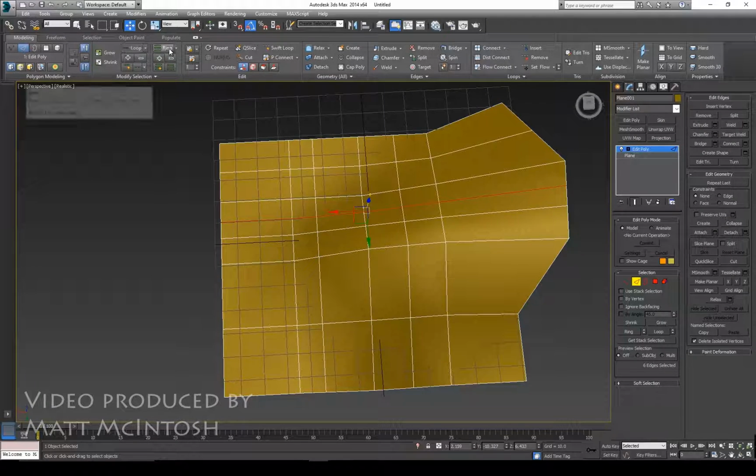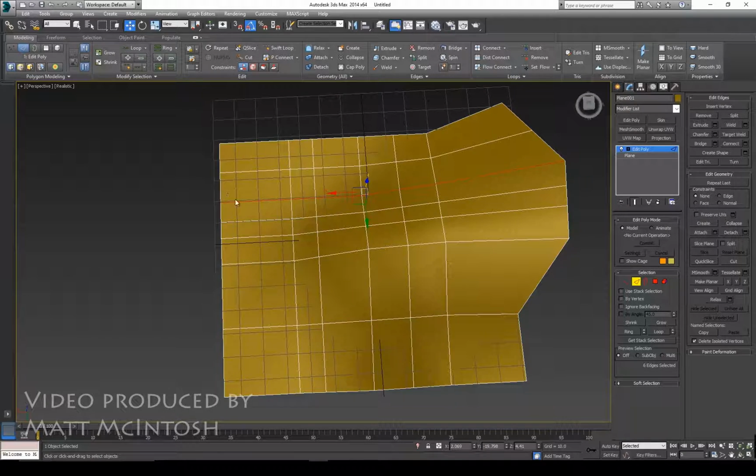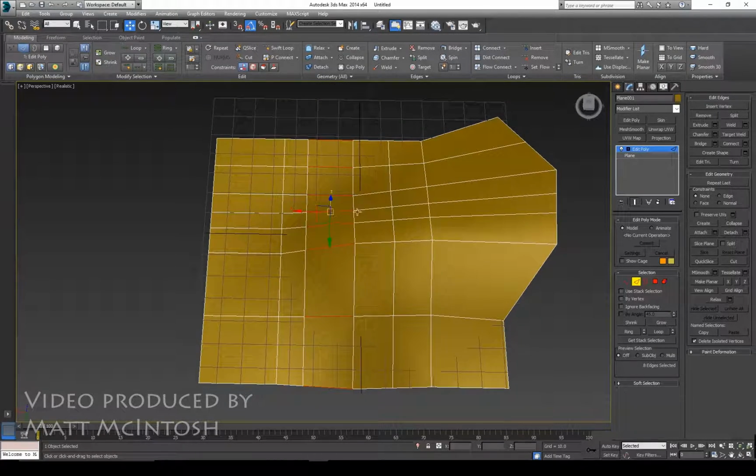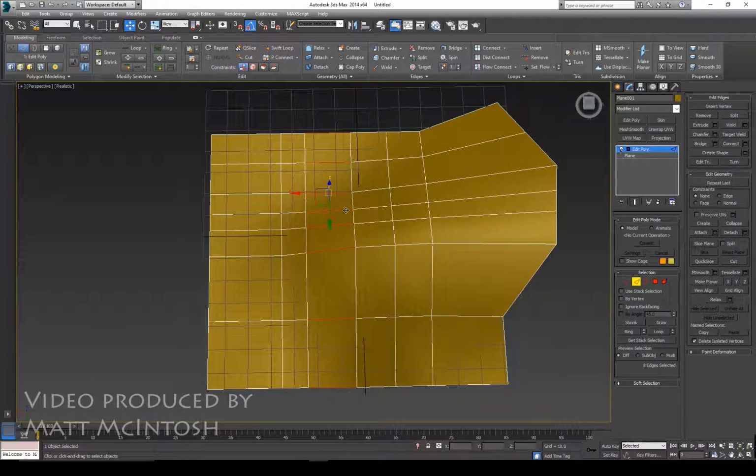Now, you've got this feature up here as well. If I select one and click on loop, that will allow it to be selected. And again, if I select one and click on ring, that will select it in the other direction. If you wanted to do that with a shortcut key, select one, press shift and select the next in the ring, and that will select everything for you. If you wanted to get rid of one though, all I'm going to do is press Control and Backspace, and that deletes any of the geometry that was in there and keeps it nice and tidy.